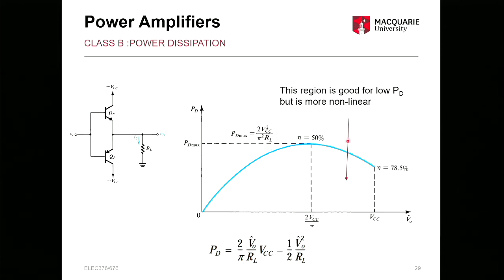But we need to be cautious if any signals that we're putting in this region are close to our VCC, so they could saturate. You need to be careful not to be operating too far along this curve, where you're going to get clipping as you get to the VCC. We've seen that in some of our previous labs. You can easily saturate with any amplifier, and it will just flatten your curve. So choosing exactly where you're going to operate is quite important.